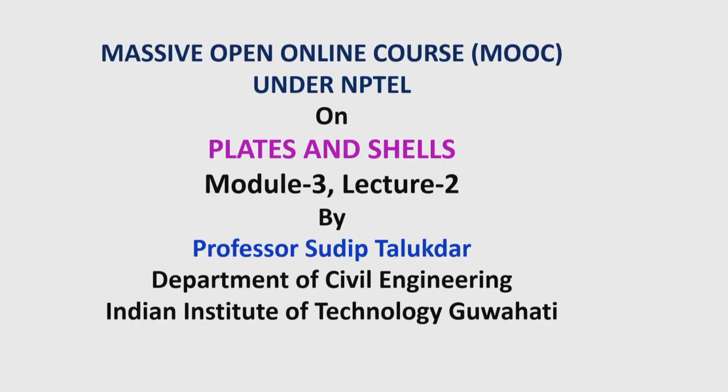Hello everybody. Today I am on lecture 2 of module 3, and if you recall my last class, I started Levy's formulation for rectangular plate, which is by nature an exact solution of the plate differential equation. In that connection we have seen that Levy's formulation can be done with the help of a single series, and the convergence is rapid, but it is applicable for certain conditions.